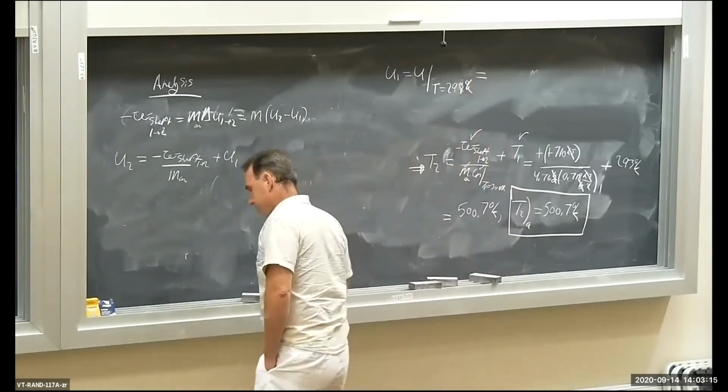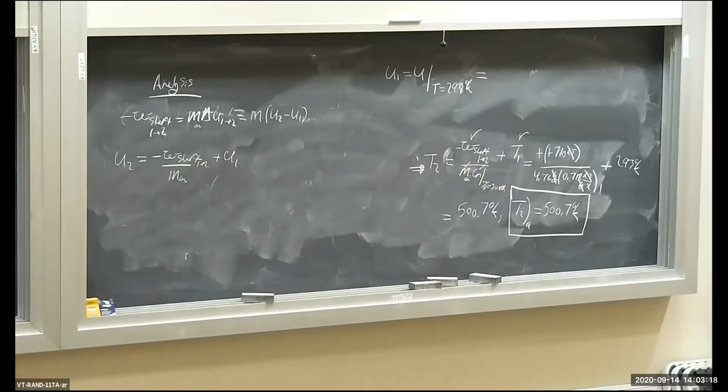So we've got the air tables here: internal energy, enthalpy, 290, 300. Internal energy at 293 degrees Kelvin is somewhere between 206 and 214 kilojoules per kilogram.